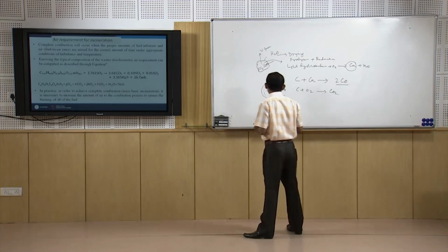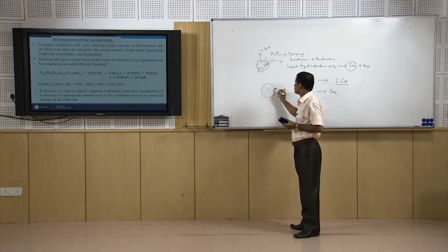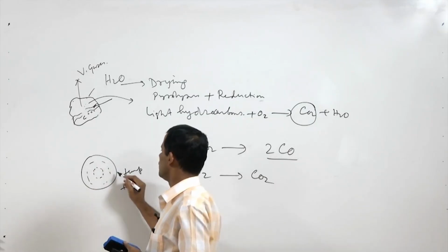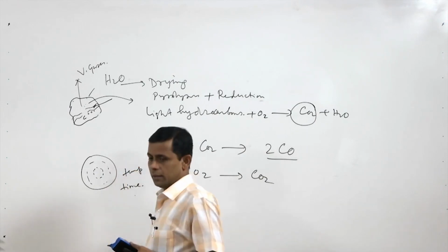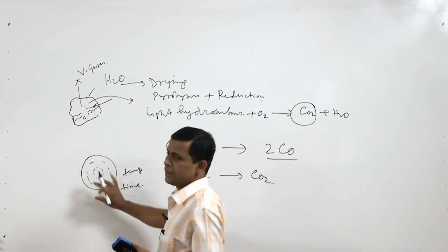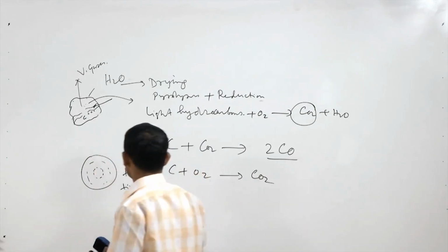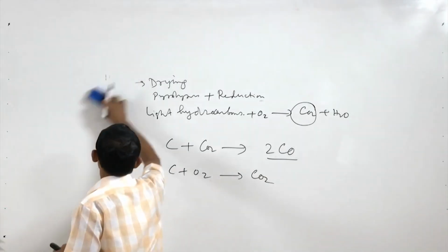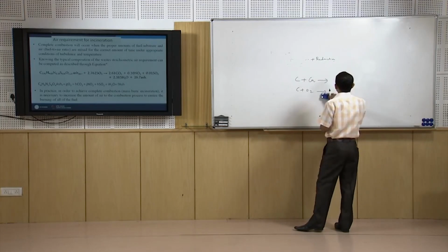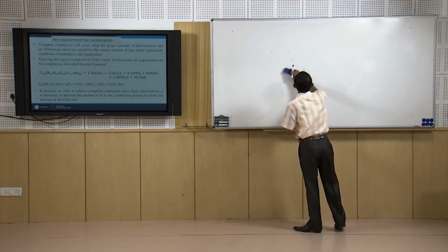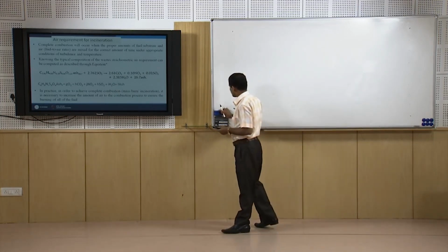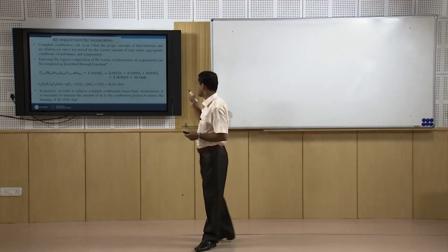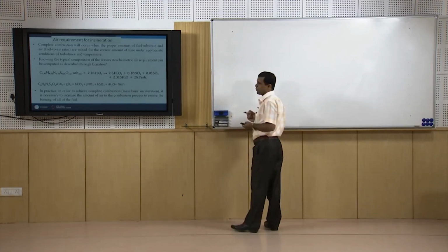Now, one thing we have come to know is that if we want to get complete combustion of the material, we have to provide excess oxygen because there are some limitations inside it. So, to overcome those limitations we have to provide excess oxygen. Now, excess oxygen or air: excess means with respect to something, and that something is nothing but the stoichiometric requirement.